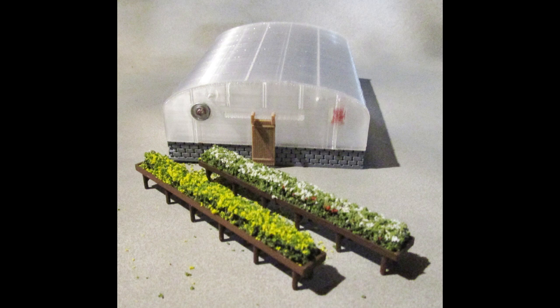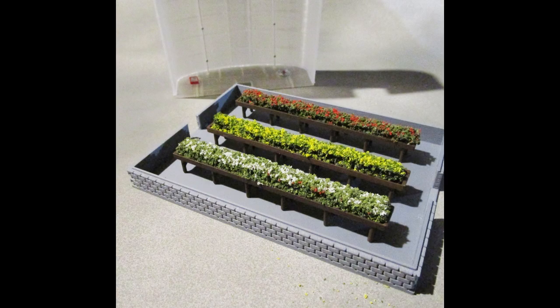I used a construction tool generator to make a lip on the top surface of the construction blocks into which the canopy would seat. The end pieces were created using the basic building's board and batten option. I then used the arch roofing generator's roof mask option to create the end walls so they mated perfectly with the arched roof.